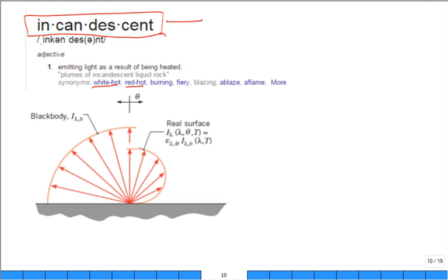Well, there's a characteristic about especially the large polar angle associated with different metals. Let's say if a metal is an electric conductor. What happens is, first of all, for an electric conductor, if you look at it, it's a metal. It has a lot lower emissivity to begin with. The normal emissivity is lower than maybe a non-conducting solid like a ceramic.